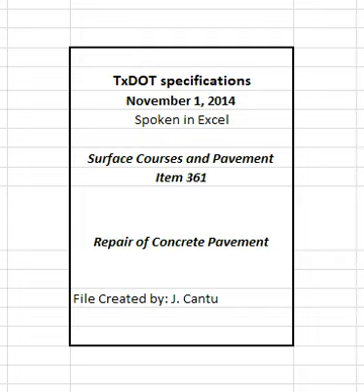Saw cut and remove existing asphalt concrete overlay at least 2 feet longer than the repair patch in each longitudinal direction when there is existing asphalt concrete overlay over the repair area. Saw cut the full depth through the concrete around the perimeter of the repair area before removal.